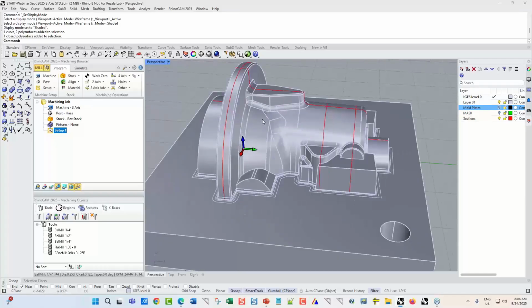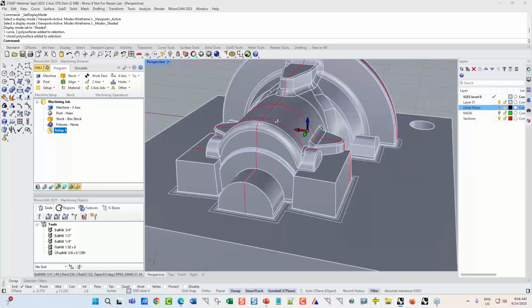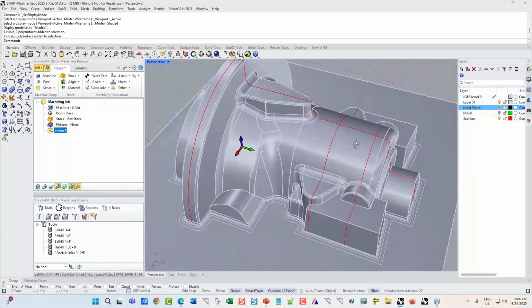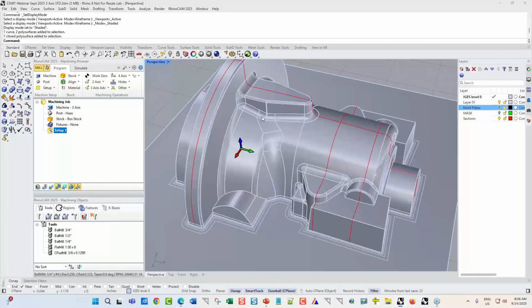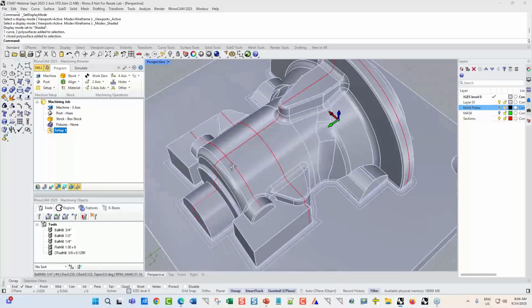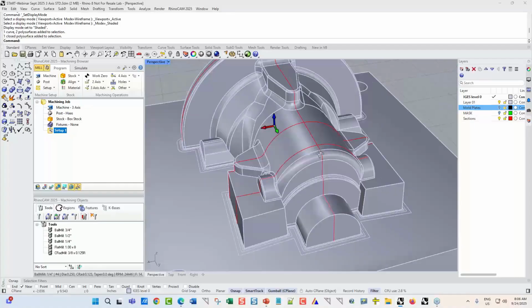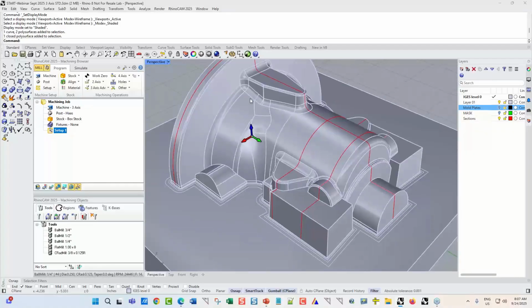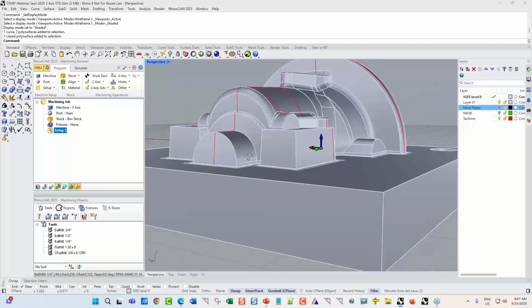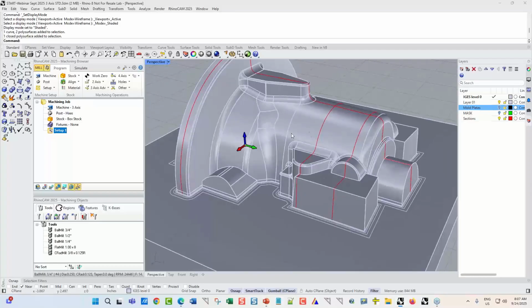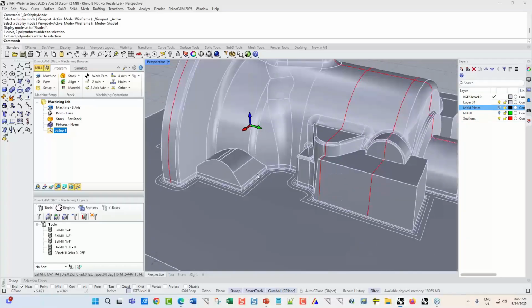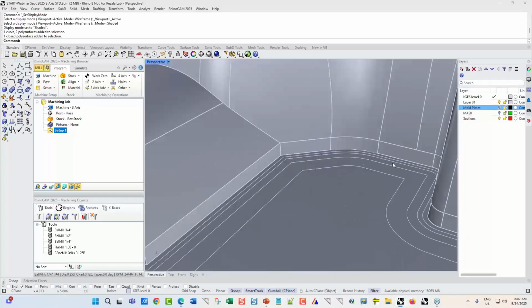So what is important with this particular set of geometry? Obviously, you have a lot of complex surfaces in here with some fillets. Nothing that we see here is really a problem with programming as far as the surfaces up here go. The primary area of concern, and you'll know this especially if you're a mold designer or a mold machinist, is this parting plane.